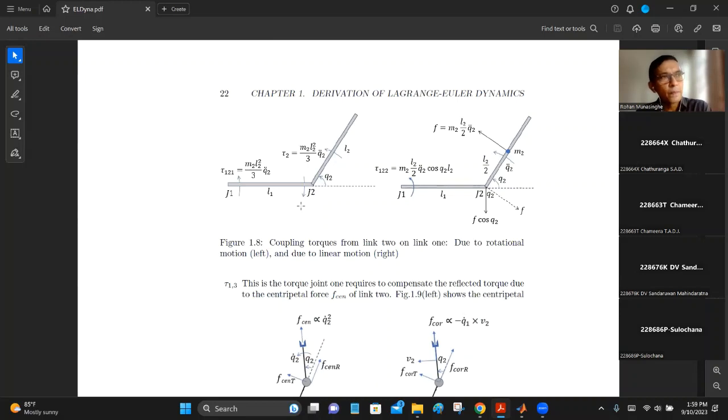So therefore, with the second link having some sort of acceleration, because it produces that torque at the end of link 1, the link 1 will deflect downward, right? If it is like this, when you start moving, the link 1 goes down. That is unacceptable. That's a disturbance. It's not what we expect. We expect link 1 to be at that configuration, and link 2 moves without any motion in link 1. So in order to do that,